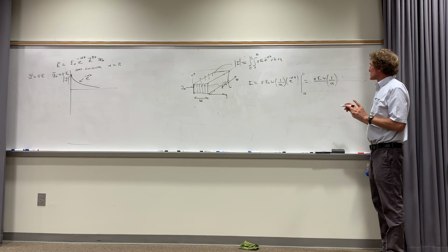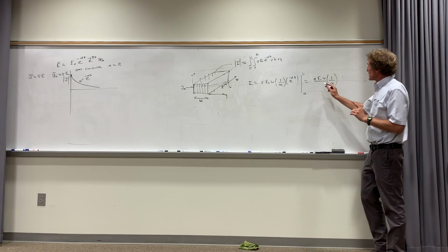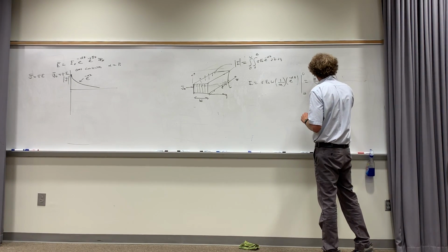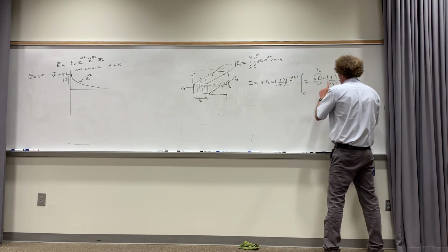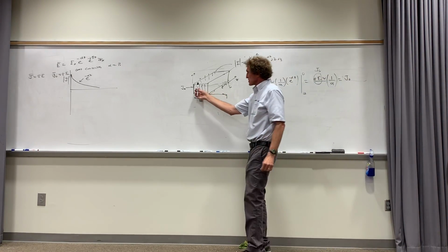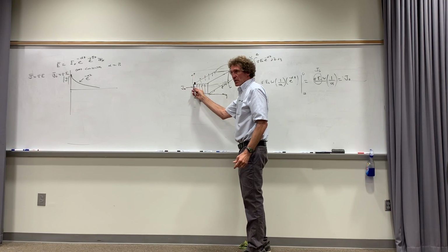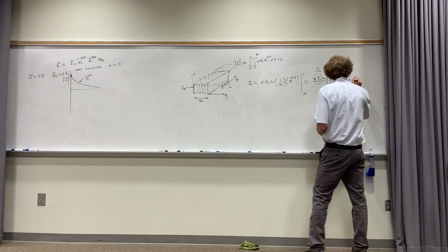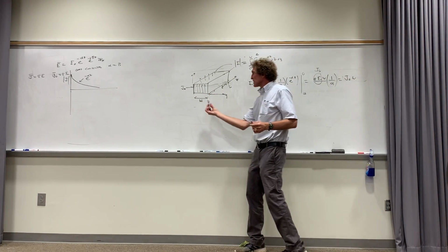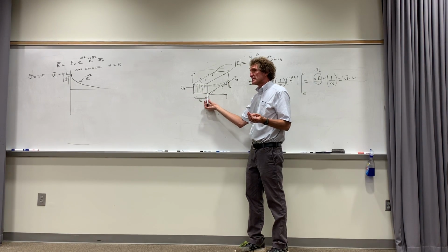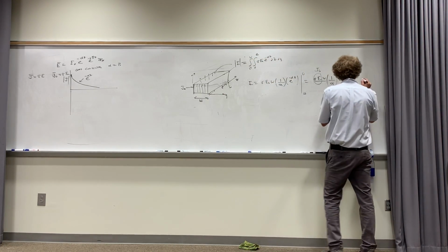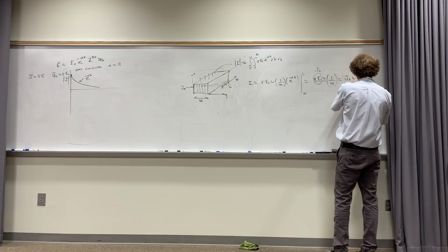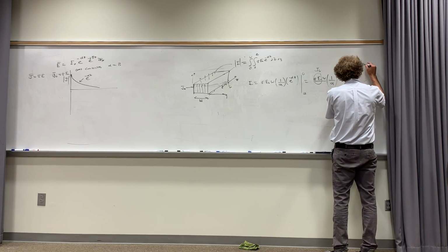What we'd like to do is say that this really is the current density J at the surface, J naught, as I like to say it. And that's J naught, the current right here, right? We're going to multiply that times the width. That would be multiplying the current density times width, but current density is really amps per meter squared, so we need a depth. You follow me? And here we use the term skin depth.